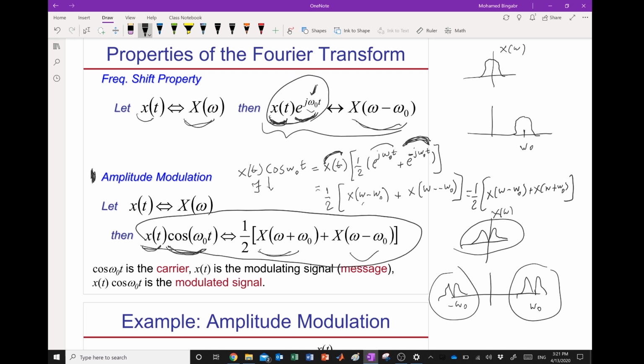And this is amplitude modulation. It's just like the AM you listen to in the radio, AM, FM. FM is frequency modulation. AM is amplitude modulation. Our speech has small frequency content. So if I need to transmit it, I need a long antenna. So what we do, we shift the speech spectrum to a very high frequency, like 100 megahertz. When you listen to 98.1 radio, you are shifting the spectrum to that 98.1 megahertz. So now I will need a very short antenna to transmit this wireless or radio frequency. And this, we call amplitude modulation.